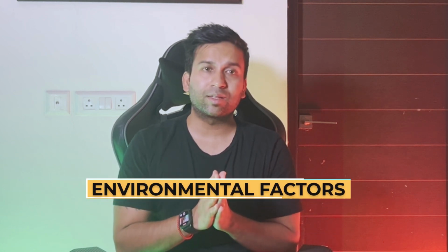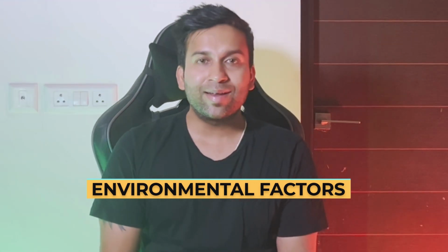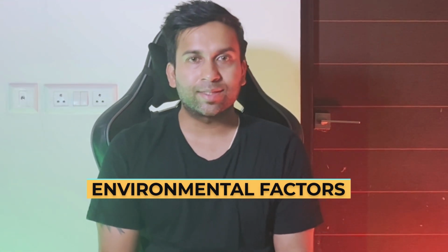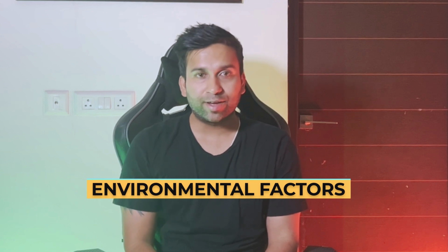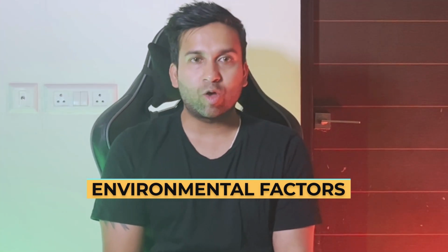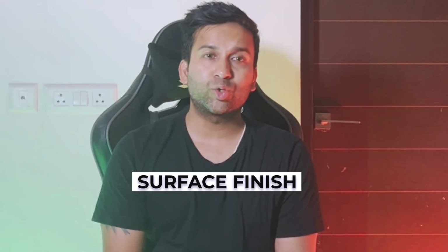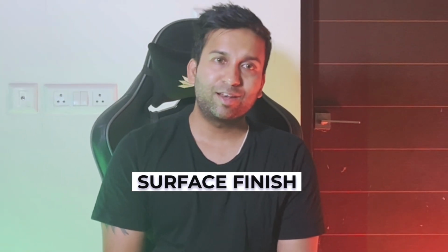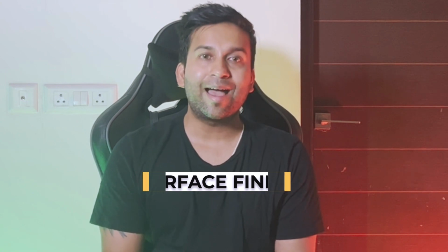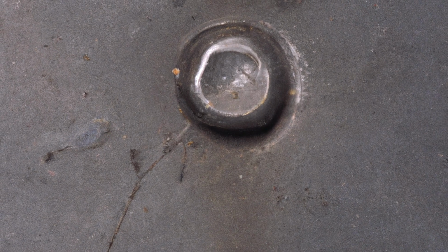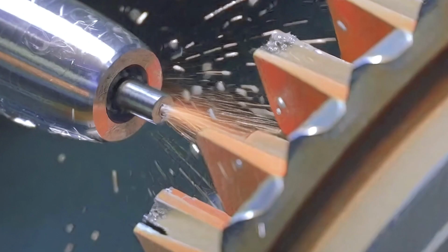Environmental factors like operating temperature, humidity, and corrosive environments can significantly affect fatigue behavior. Elevated temperatures accelerate crack growth rates, moisture promotes corrosion fatigue, and chemicals can interact with compounds, changing material properties. Surface finish and treatments are also very important considerations. Defects like scratches and notches act as stress concentrators, reducing fatigue resistance. Shot peening and surface hardening treatments can actually induce beneficial compressive residual stresses,